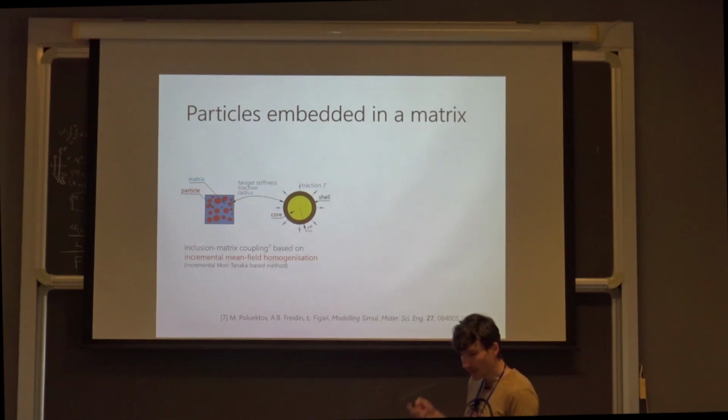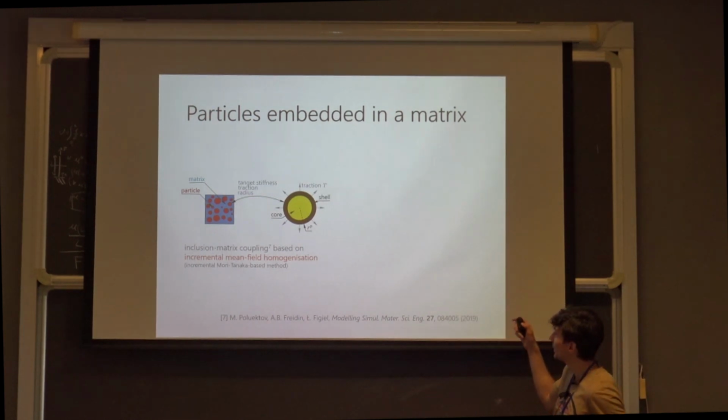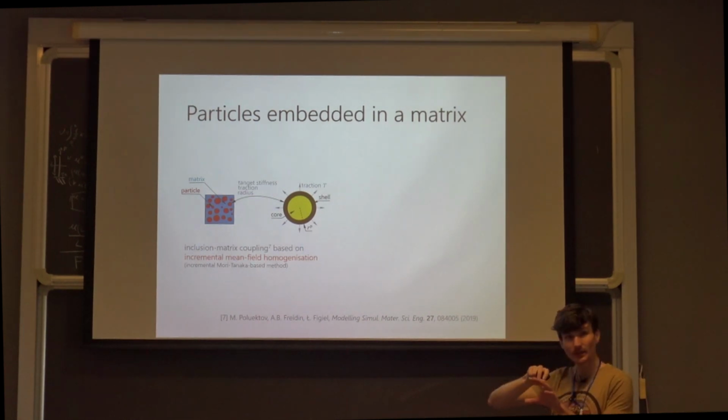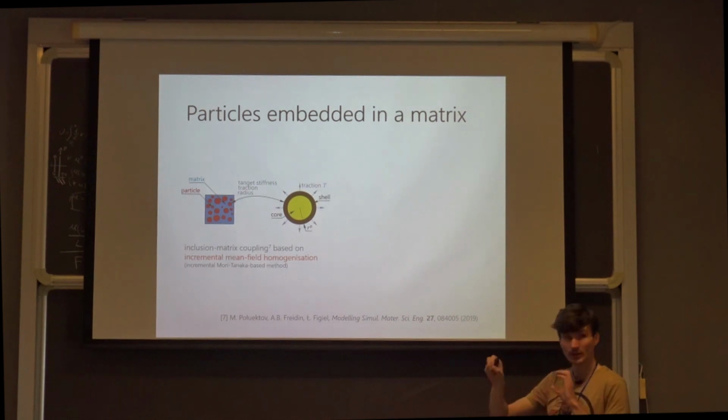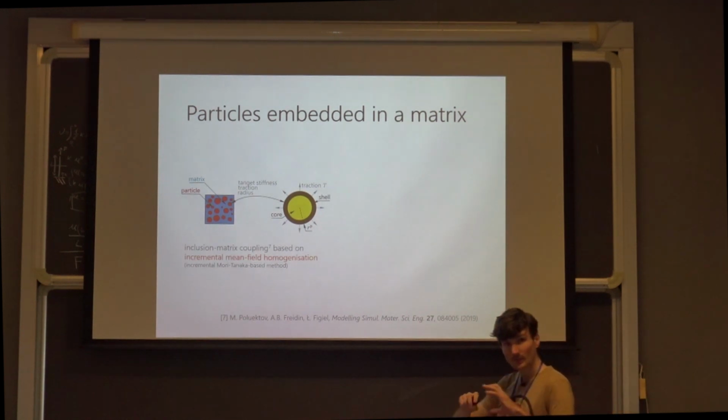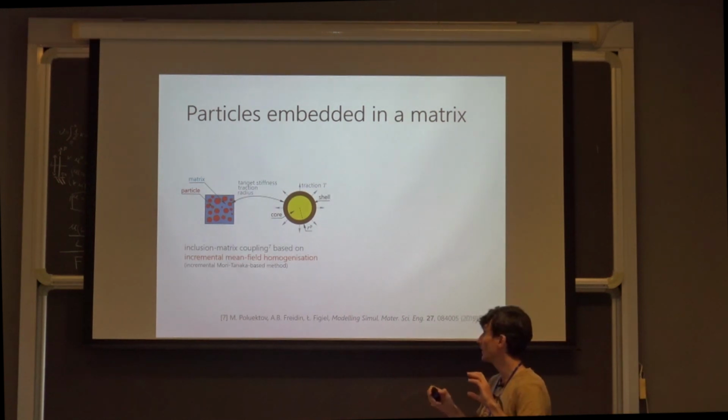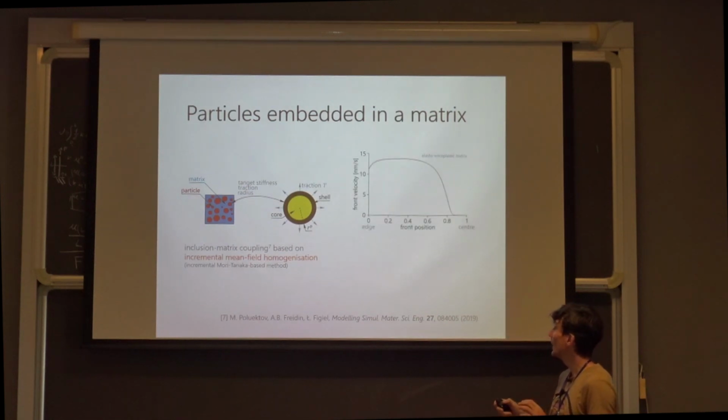We then looked at a model where we embed the particles in the matrix. We did this in a mean field way. We performed mean field homogenization. We used the Mori-Tanaka scheme to surround particles with a viscoplastic matrix.